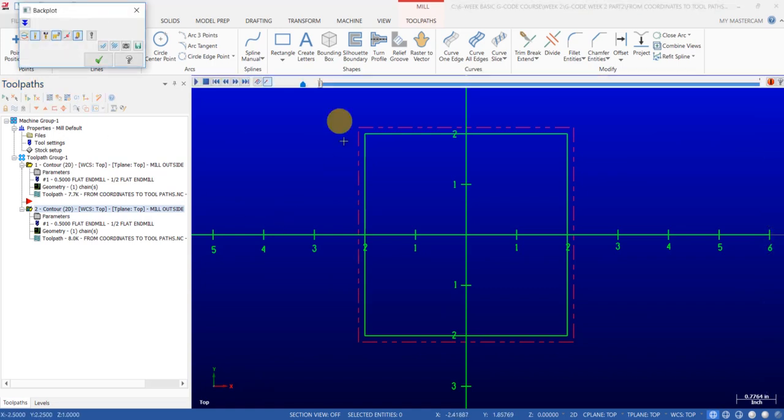So now the tool is coming down away from the part. So if we look at the coordinate down here in the lower left hand corner, my X value for this position is X minus 2.5. So I've actually added an additional 1/2 inch on the center line of that tool. And then also notice that the bottom of my tool is now even with the outside of my part. So this being a 1/2 inch tool, I've had to offset it a 1/4 inch, 250 thousandths.